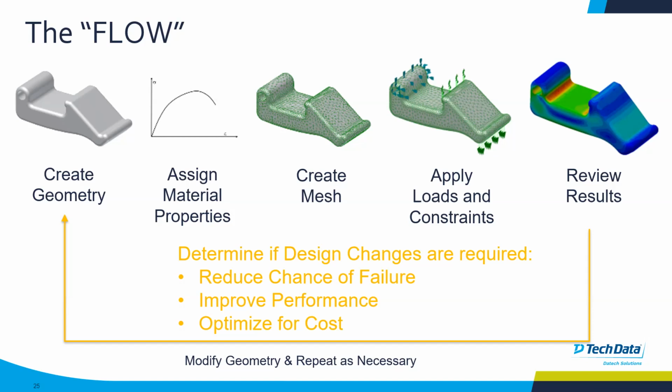And what's good is that it's integrated within Inventor. So you just make the edits and update the mesh and also the studies, and it will recalculate again. You can do this multiple times. You can also combine multiple studies together. We call it a subcase. For example, if you want to test thermal and also stress, you can create a thermal study first, and then create a stress study after that. So you can run the simulation together and get the result for both studies.